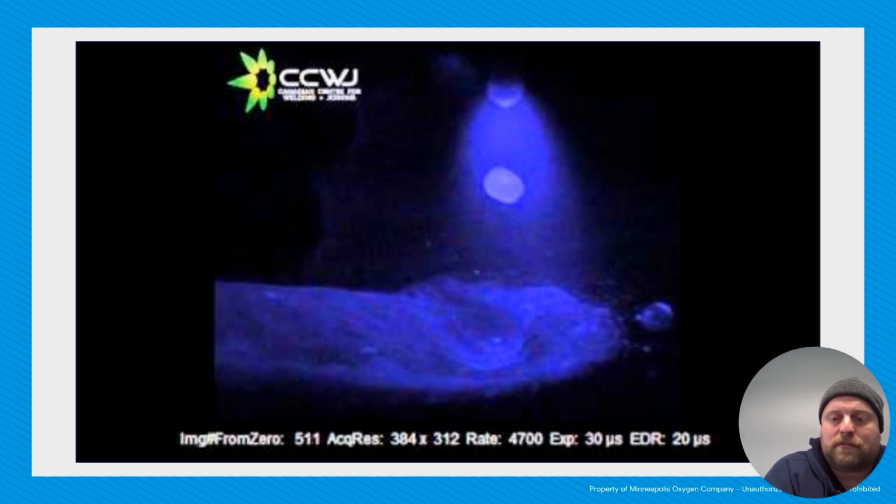This is super useful for out of position welding, because then we can get the results of the spray, which is increased deposition and penetration, but we can do it out of position. The heat input is less, so you can really help to prevent some warping. And then the other cool thing, which I've learned recently, is that pulse is also a great option if you need to reduce your fumes.